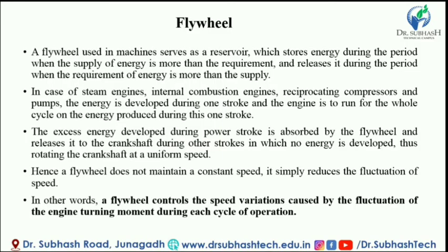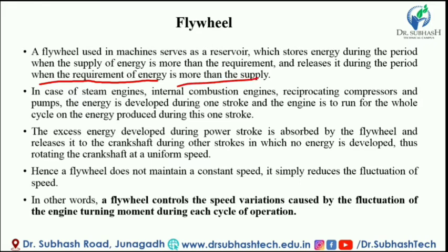First we see what a flywheel is and how it is used. A flywheel used in a machine serves as a reservoir. What kind of reservoir? A reservoir of energy, which stores energy during the period when the supply of energy is more than the requirement, and releases it during the period when the requirement of energy is more than the supply.